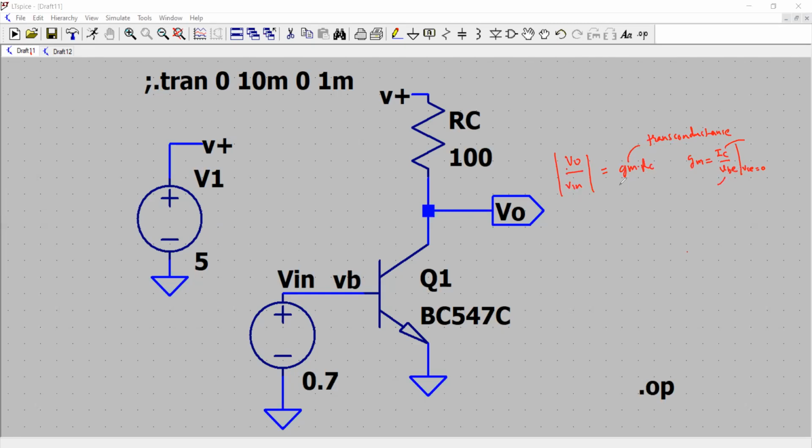So we see that the gain is dependent on intrinsic parameters such as the transconductance of the circuit. The circuit is also said to have a limited dynamic range, because if you try to exceed that, the output exhibits distortion, and there was a stability issue as well. So to fix this,